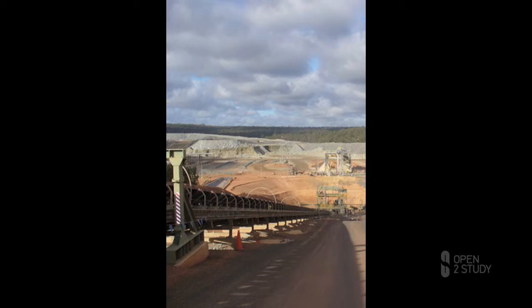An alternative method of transport for the overburden is the belt conveyor, and Stephen mentioned it in the previous module. The belt conveyor, compared to the truck haulage transport system, is more energy efficient and less labor-intensive. The method is often combined with dragline and crusher excavation methods, and it represents a good cost-effective solution.